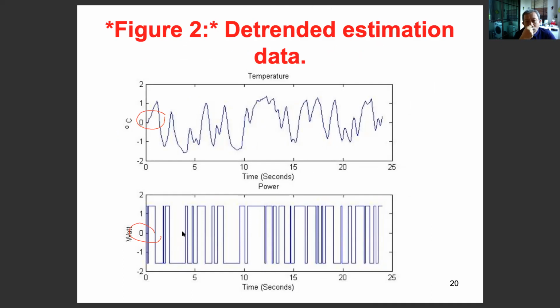We clean the data. It is like when we buy fish, we clean its stomach, we clean off the blood, the unnecessary items, and only then we cook. So it is the same with system identification, we need to pre-process. We remove the DC offset first, detrend, remove outliers, then the data is clean, and then we can analyze it to get the mathematical model.